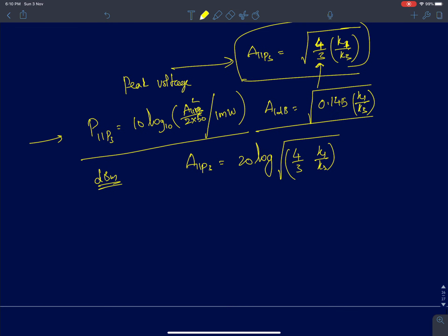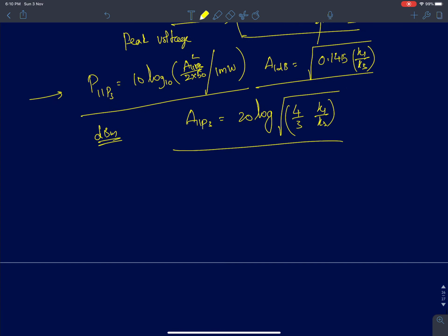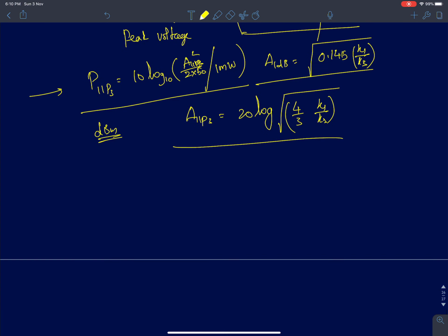So it is that level at which the intermodulation power becomes equal to the input signal itself. Normally, in most engineering and RF applications, we always plot signals with respect to logarithms because it's easier to interpret the results.